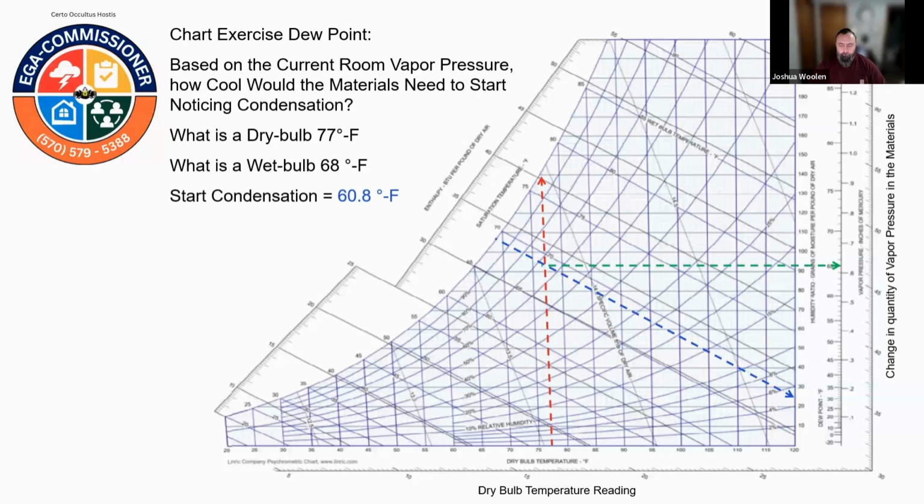Now, just to be clear, the dry bulb temperature is defined as the temperature of air measured by a thermometer. And when you use a thermometer, use one that is quality and accurate. It's important that you use an accurate device, freely exposed to the air but shielded from radiation and moisture. And we understand what that means, right?